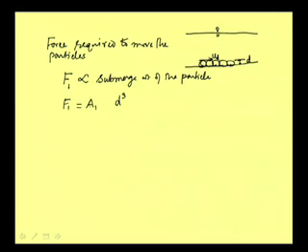As we are already using a proportionality constant, we can keep it as proportional to the volume. Then it is the mass, and since this is the submerged weight we are talking about, we write rho s minus rho, which is the submerged density, and then we multiply this by g, that is g into (rho s minus rho).